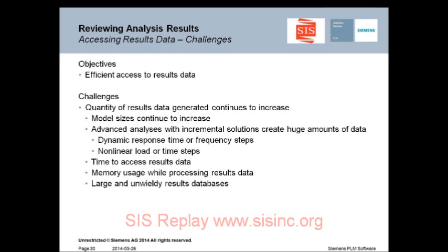Once you get into more advanced types of analysis, again, the amount of data will increase. So rather than a single solution for a static analysis, for example, once you get into a transient response, you get a single solution for every single time step. So you can see that's going to very quickly create a vast amount of results data. Similarly for nonlinear, maybe load steps in that case, or frequency steps if you get into a frequency response. So a lot of data to get through.